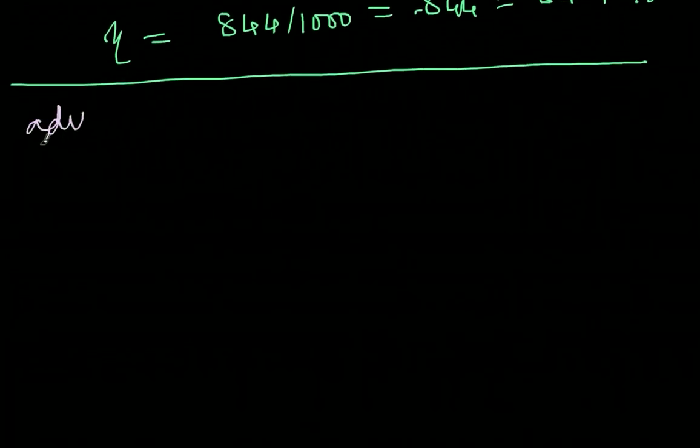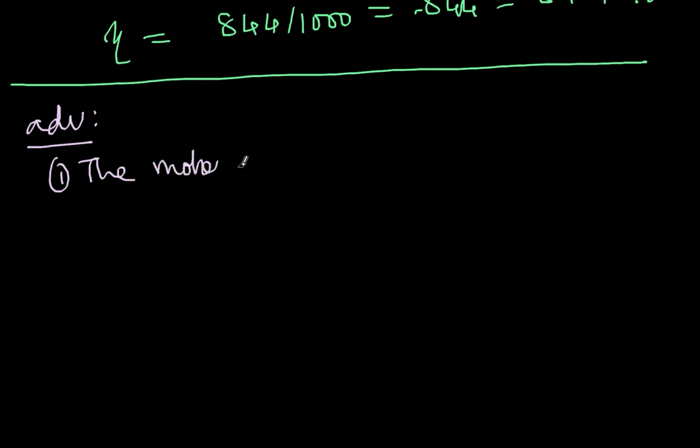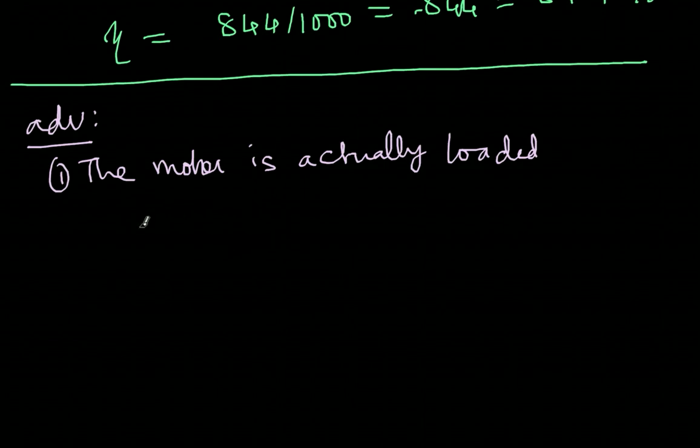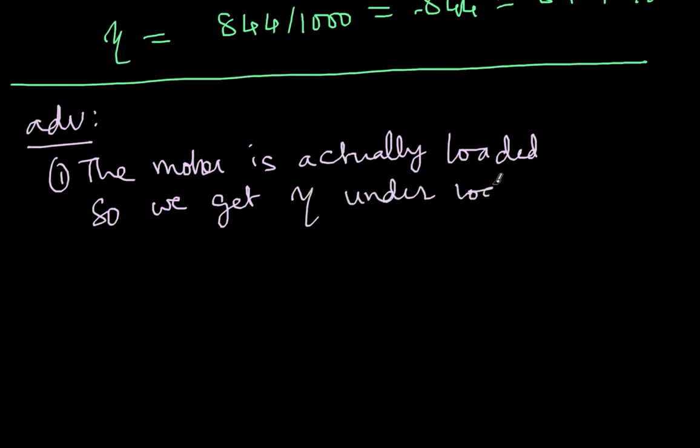The advantages of the brake test include that the motor is actually loaded. That means it actually consumes that much power. So we get efficiency under loaded conditions. That's one of the advantages. And the second advantage is that it is simple and easy to perform.